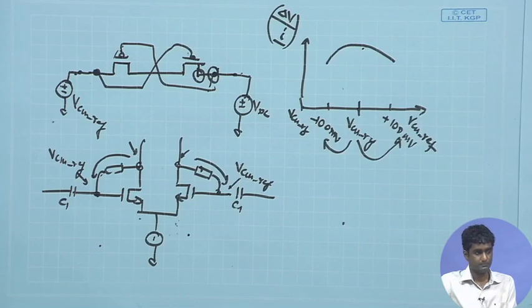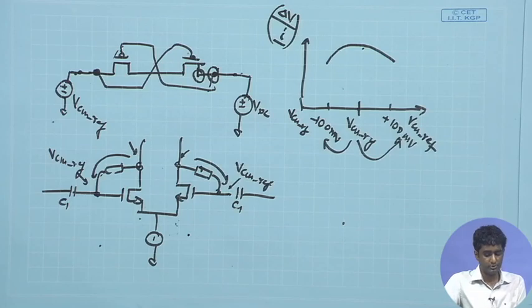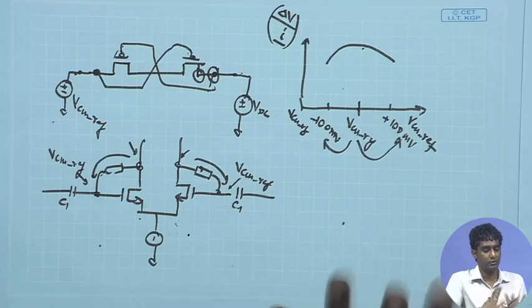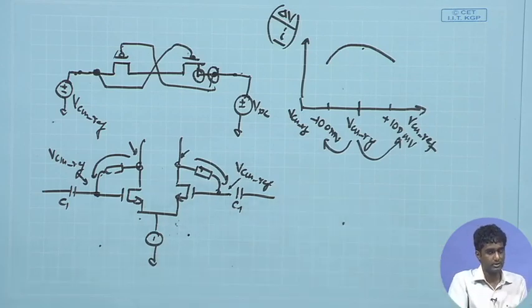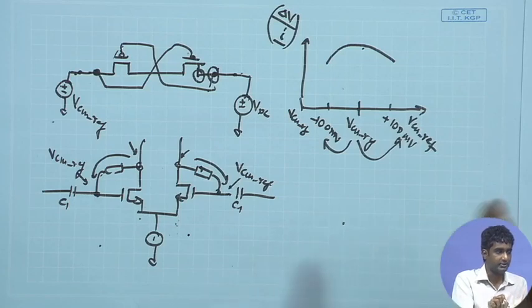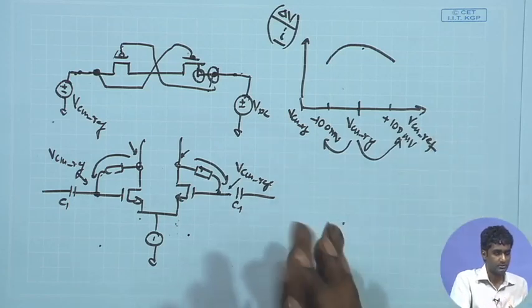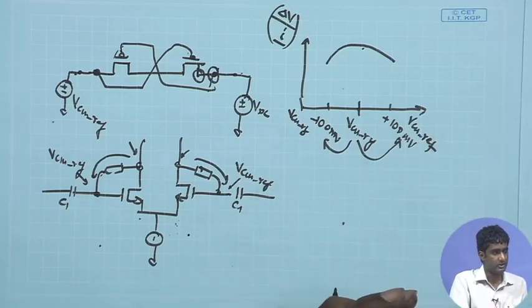So, how to initialize? By MOSFET switch, that is another way, but you have simulation options also there. We will check that in the LT-SPICE or even in Cadence. You have simulation options where you can apply initial conditions to some nodes. Even in the SPICE simulation, generally when you write codes for the SPICE simulation, there also you can specify initial condition using init statement. You can put some initial voltages at required points.